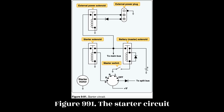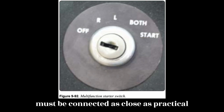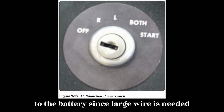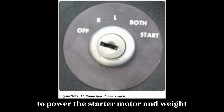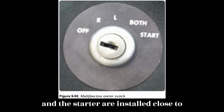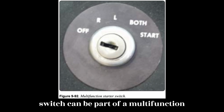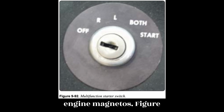Figure 9.91. The starter circuit must be connected as close as practical to the battery since large wire is needed to power the starter motor, and weight savings can be achieved when the battery and the starter are installed close to each other in the aircraft. As shown in the starter circuit diagram, the start switch can be part of a multifunction switch that is also used to control the engine magnetos.